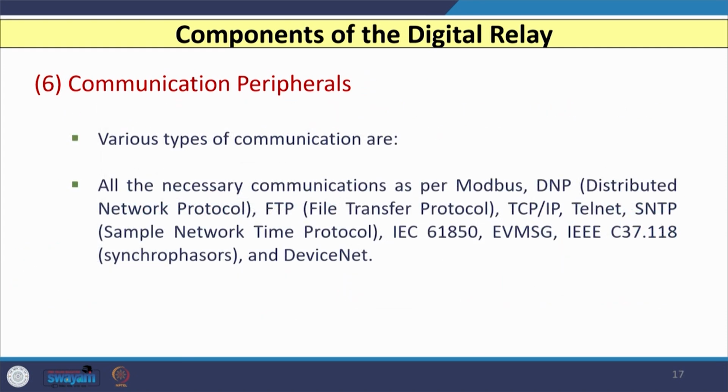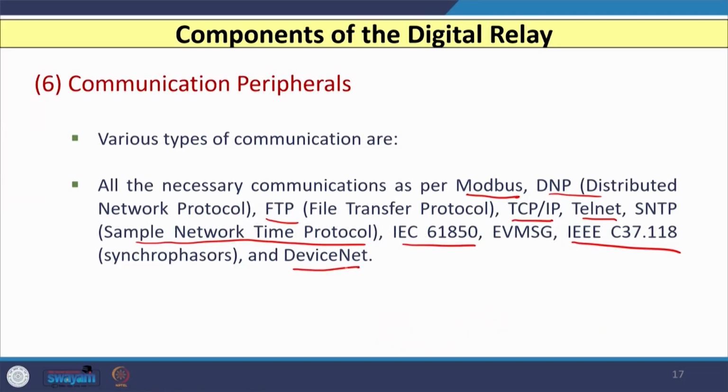So, different types of communication are possible. These are Modbus type of communication, maybe Distributed Network Protocol is also there, File Transfer Protocol is also there, TCP/IP, that is Transmission Control Protocol and Internet Protocol, Telnet, Simple Network Time Protocol known as SNTP, and IEC 61850 and IEEE C37.118, which is used in synchrophasors or for PMU, along with DeviceNet type of protocols.